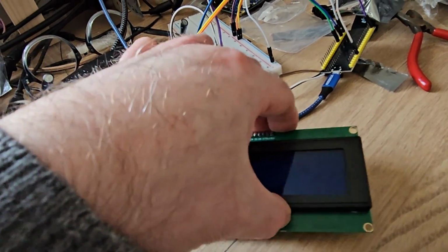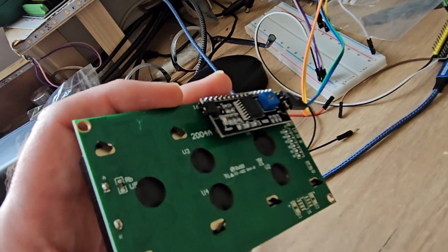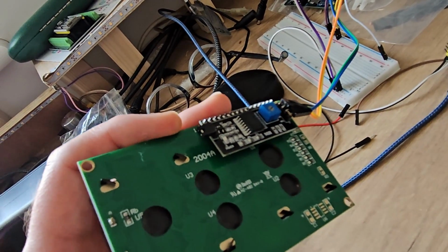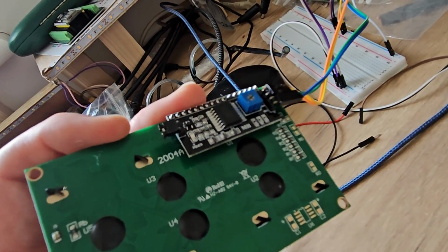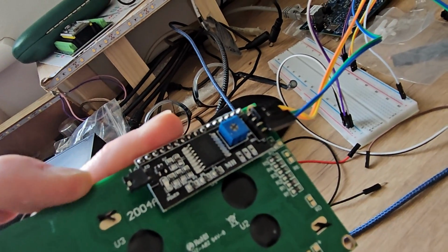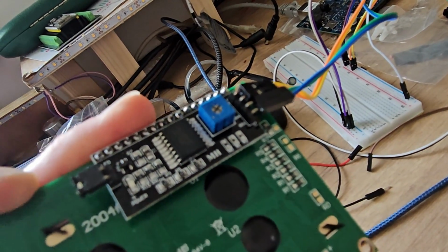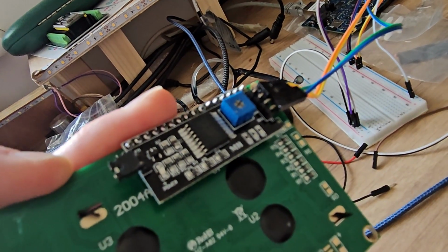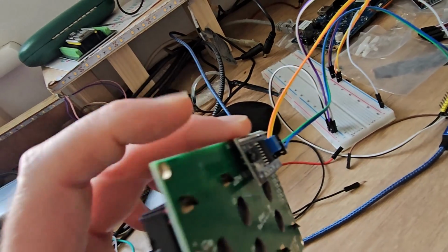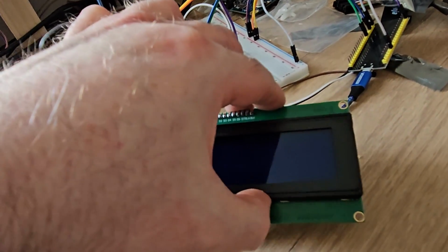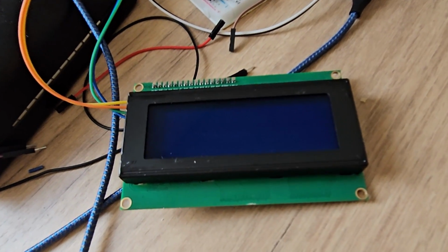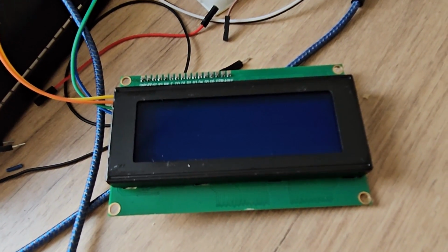While I've got it upside down, one thing to note: I got it all rigged up and put a test script on it, and it didn't work. The screen lit up, but nothing happened. I was messing about with cables and trying different addresses, and then I suddenly remembered that these things have a contrast setting on the back. It's that little screw there. Just out of curiosity, after I tried everything else, I tried turning that, and suddenly the contrast was set and the screen displayed properly. So to save anyone else any time, if the screen's lit up and there are no words on it, try twisting that screw a bit until some words appear.